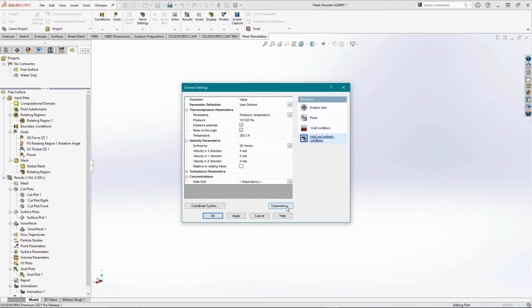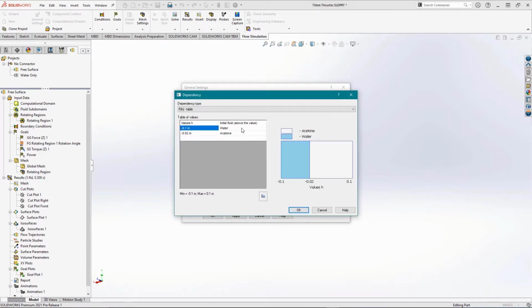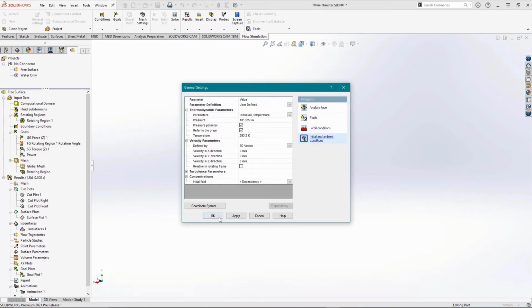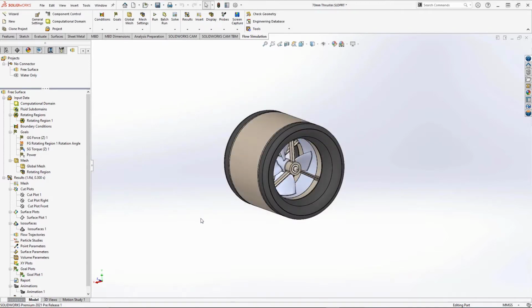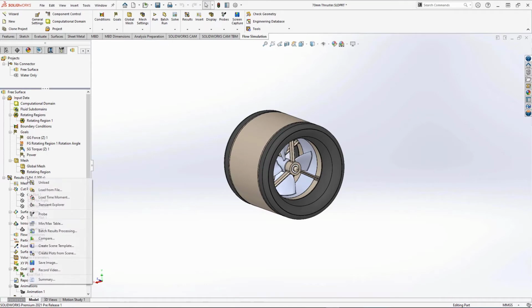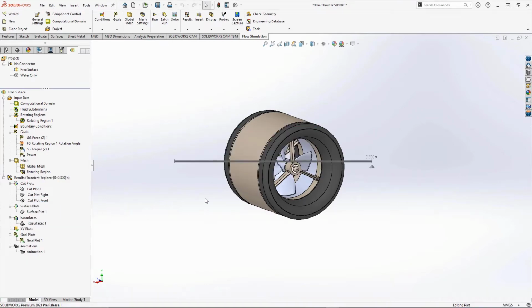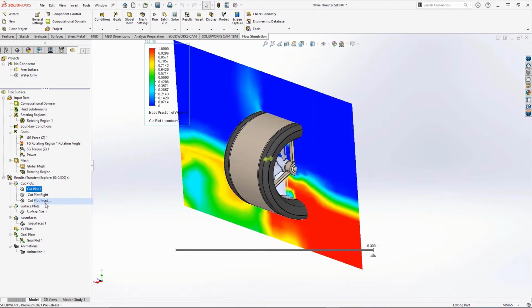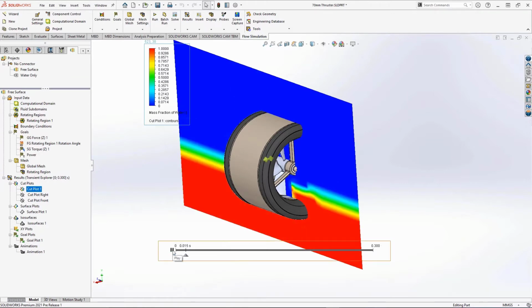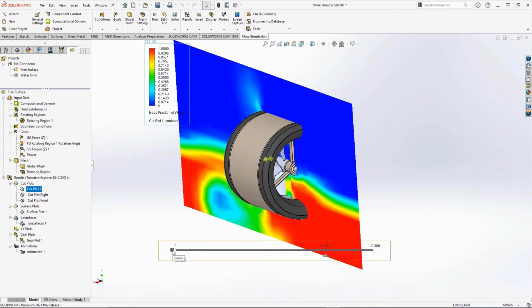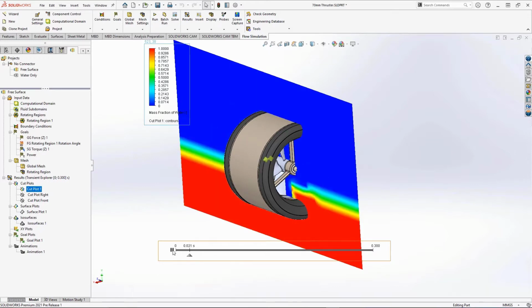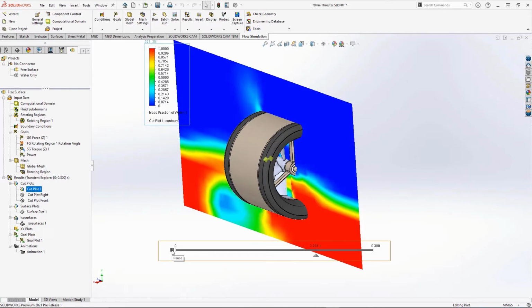Here I've got a concentration that's a mixture of water and acetone. Now I mentioned this is a transient, time-dependent study, and in that case I like to look at the results with the Transient Explorer enabled. Just a right-click on the results folder. This allows me to review any of my plots as they change over time without having to get into the interface of the animation suite or deal with keyframes or timelines. This cut plot also then becomes a sanity check that my simulation performed as expected. And it's similar to what you can watch while a simulation solves if you're just talking about cut plots.